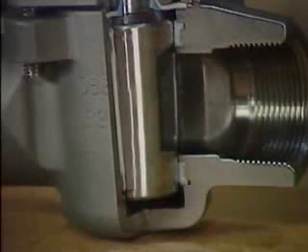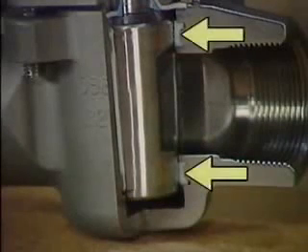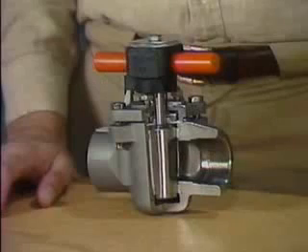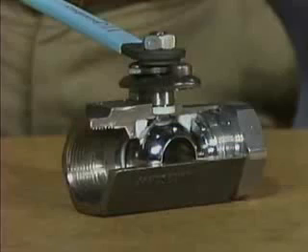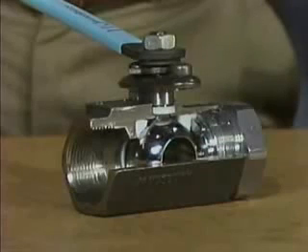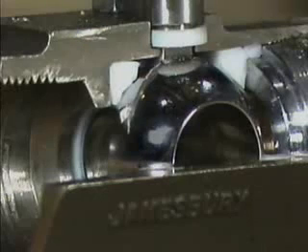This plug valve, for example, has a plug that's enclosed in a sleeve that's made of a Teflon-like material, which is self-lubricating. Non-lubricated plug valves are especially useful for applications in which lubricant must be prevented from contaminating the fluid that moves through the valve. Like a plug valve, a ball valve has a disc with ports that are aligned with the inlet and outlet of the valve body to either allow or stop flow through the valve. As its name indicates, a ball valve's disc is called a ball because of its shape.